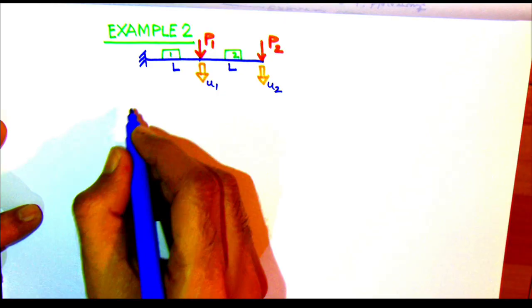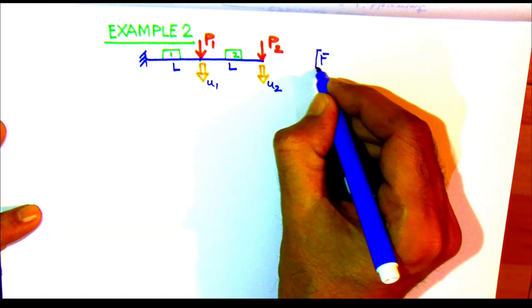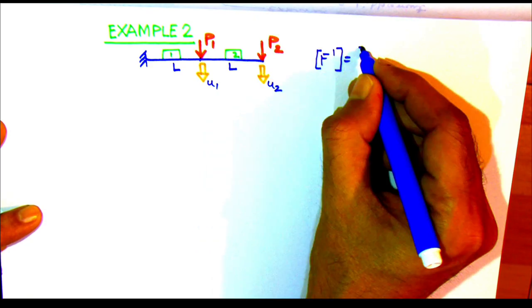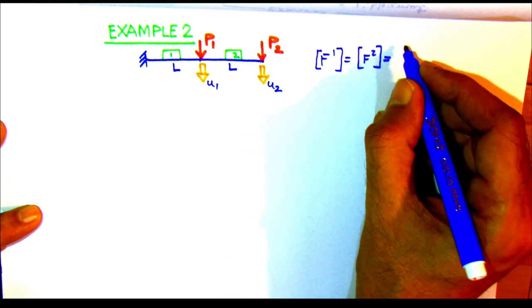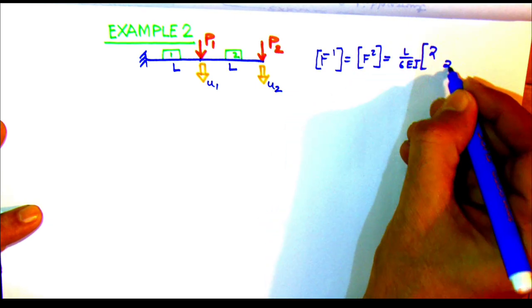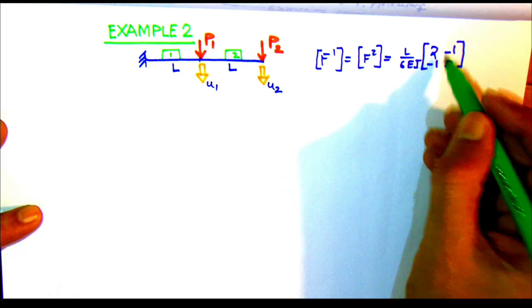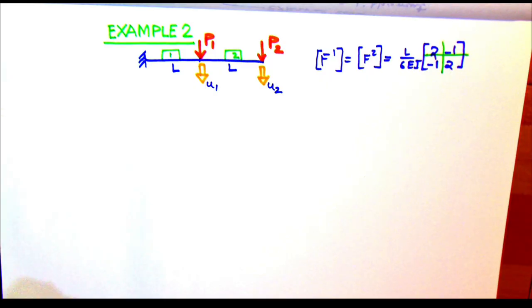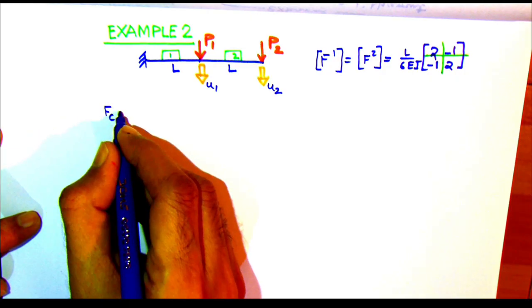So here the external displacements' positive directions are defined by the lines of action of the forces along which we are measuring them. Here the external forces P1 and P2 are downwards, so the displacements are also positive if they are downwards. When talking of the external forces and the external displacements, the regular sign convention of clockwise or anti-clockwise, towards the positive x or positive y or towards the negative axis, does not work. So this must be remembered.